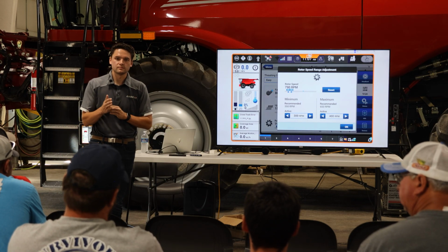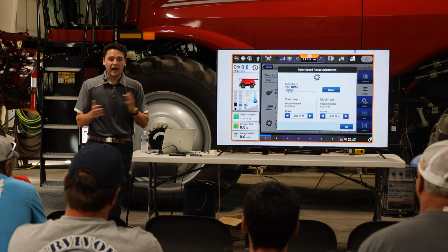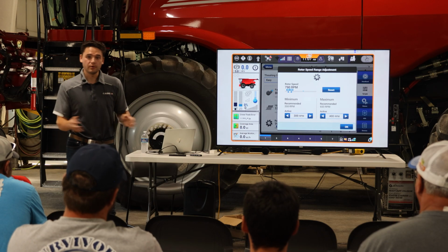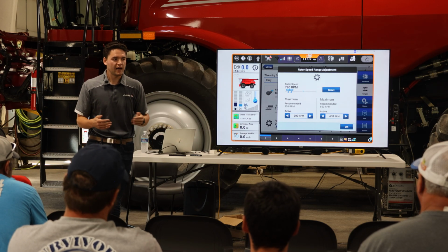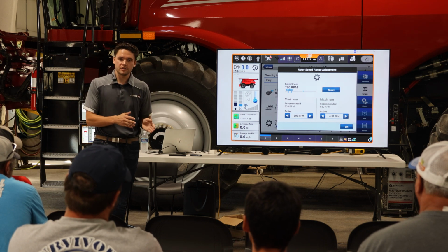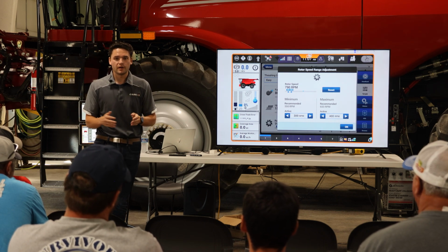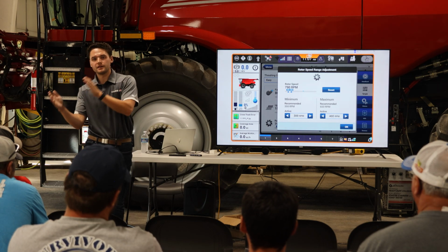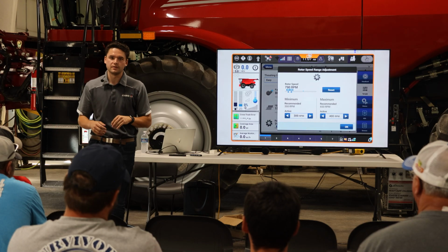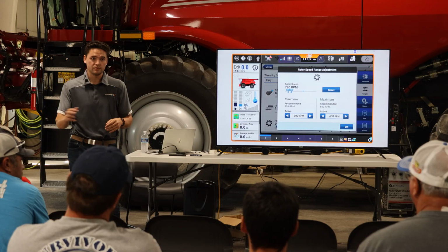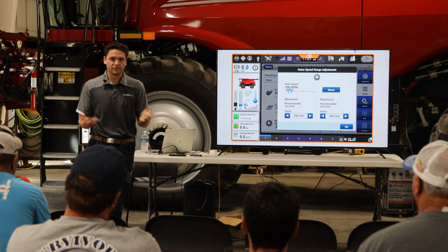What do you recommend changing it at a time? Small adjustments. I'm a very big fan of being conservative when I'm doing range adjustments, because I would rather make small incremental adjustments, let's say 5 times, rather than making 2 large jumps and overshooting and then coming back and doing 4 jumps backwards to get to the set point that I like. Because you might find if we're doing small increments, we might do 1 or 2, and then it's fine.